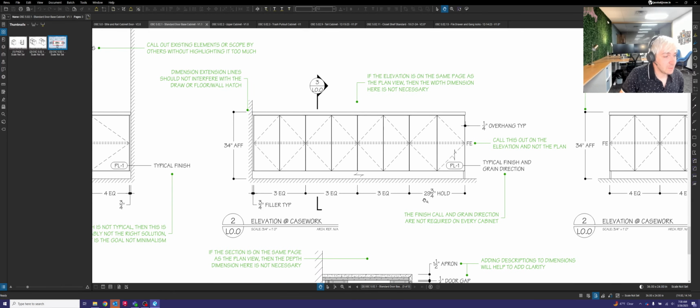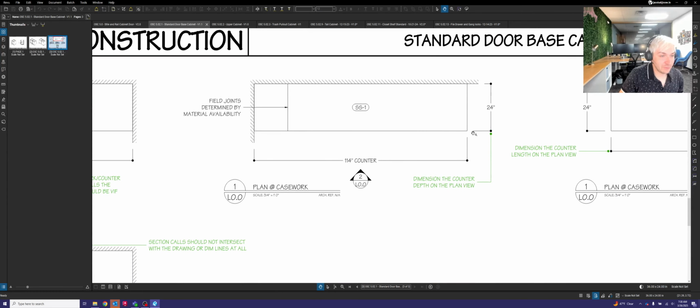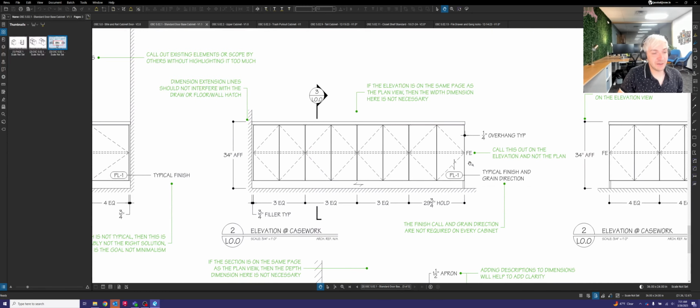All right. And so going back to the top-down view, you can see there is no wall on the right-hand side. So these cabinets are kind of open to the room, meaning that one of the vocabulary terms I have for you here is what's called a finished end. On our drawings, we'll label that with an FE to the side of the cabinet that is going to need to have a finished end.